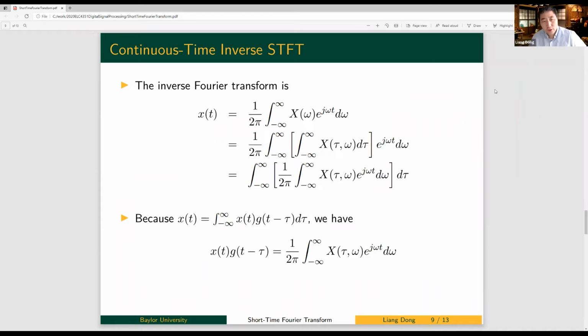So we are using a short-time Fourier transform, and we are kind of doing it in a dynamic way. Every time I am just taking a very local window in time and finding its frequency components. Because the signal is time varying, it changes, so I use that to track all this frequency change by shifting this window.